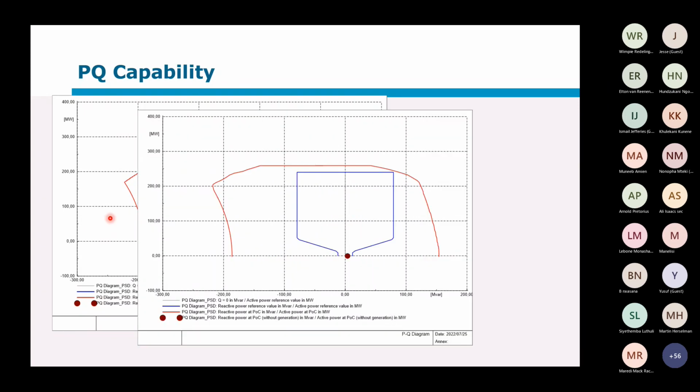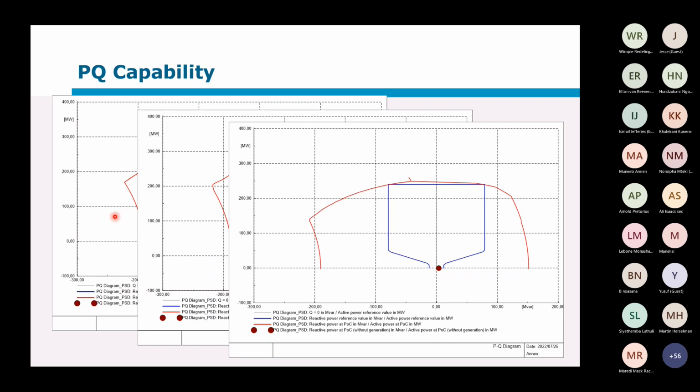And this was done at different voltage levels. You can see that for the low voltage starting point, it actually clips this part here. So in this case, the generator has to adjust his design so that he doesn't clip the corners there and is fully grid code compliant. So he has to now either take a different inverter or add a few inverters or something like that.